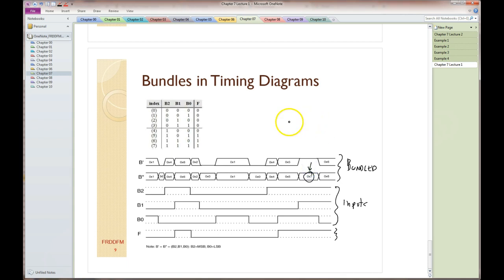And additionally, I like using this escape character of 0x, which indicates the number that follows it is going to be interpreted as a hexadecimal number. So for example, 0x7 equals 0111, 0x3 equals 0011, etc., etc. I use that everywhere. Oftentimes you see other notation in timing diagrams. Hex is quite popular in timing diagrams. It's represented in a couple different ways. I'm choosing to use the 0x.